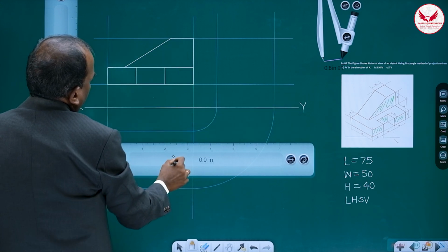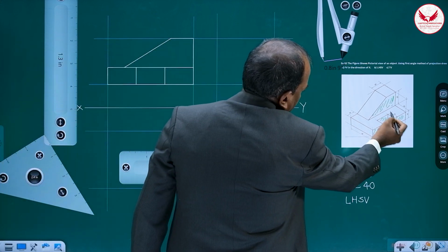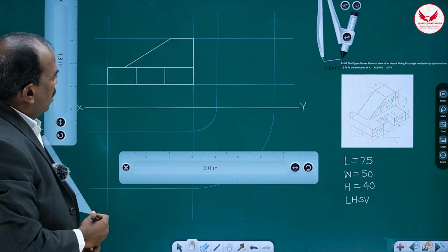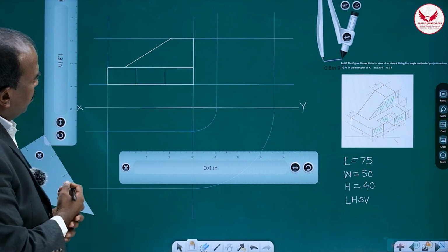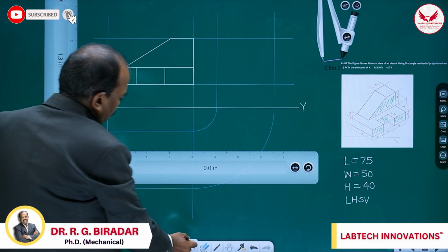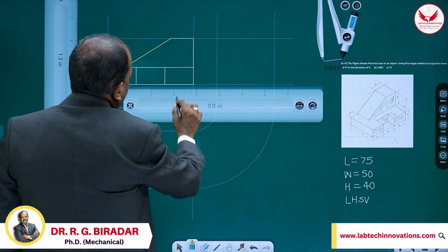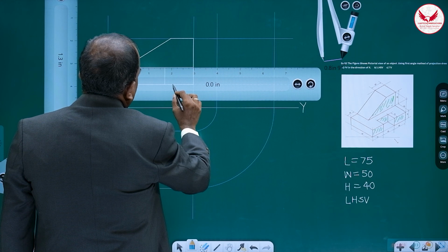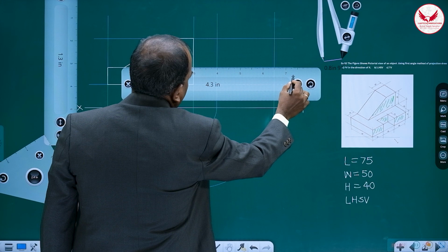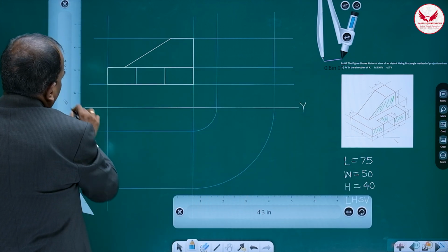Now see, the 4 parts are there. These 3 rectangles plus this, just like a trapezium. Correct? So it is the complete front view. And once we draw the front view, my suggestion is: from the front view, transfer horizontal lines to the side view. Only a single additional line is there. Transfer it in the side view. When a light line is there, extend beyond the blocks.